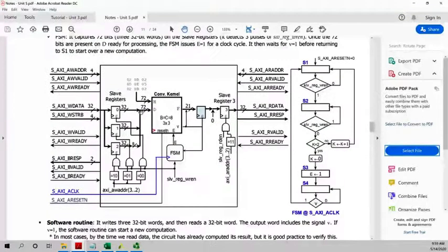We have to feed data here, exactly 72 bits, and once enable is asserted, the block starts the computation, and after a while, I think it's about 6 cycles, the output appears on F. It's 20 bits, and the output is going to be signaled by V, the valid output. So that's all we need to do, okay?